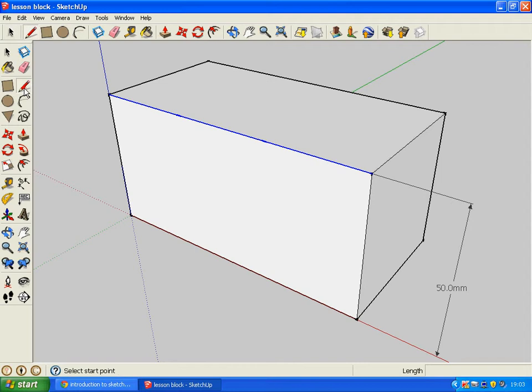Okay. Now I've got that divided into 3 segments, I'm going to use this tool here, which is the line tool, and now I can navigate along this line, and you'll notice that as I come along I'll get a green circle and it will say end point. At that point I know that I'm 1/3 of the way along. Now if I drag my mouse across the cube, I'll get a green line, and again this is a great feature of SketchUp. It's intuitively asking me, do I want to snap to that line in the green plane. That way I can guarantee that my lines are parallel in my cube. Okay, and again as I come across to the next edge, it asks me, do I want to connect it to the next edge? So I'm just going to let go with the left hand button and that will connect.